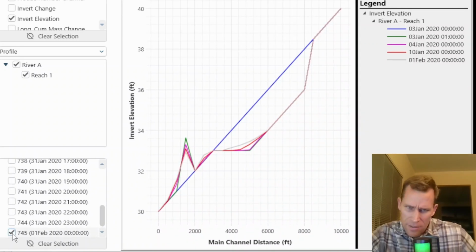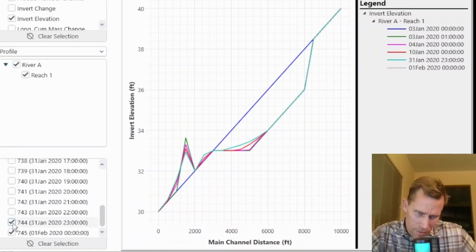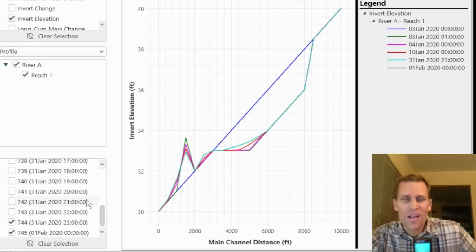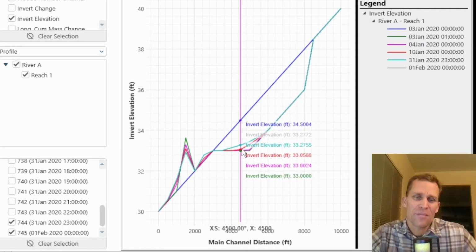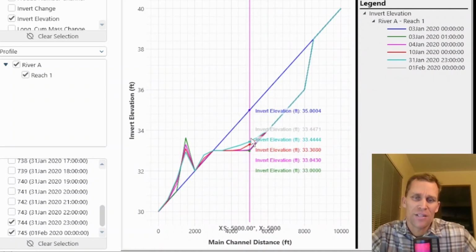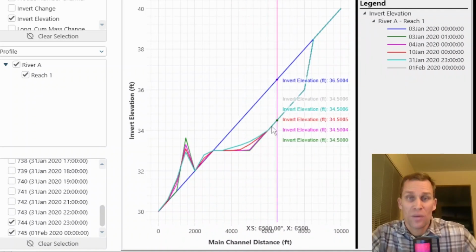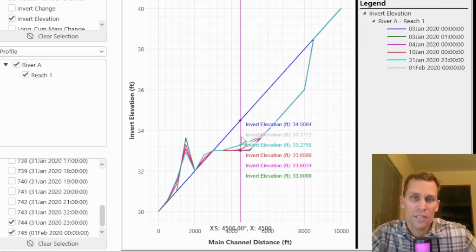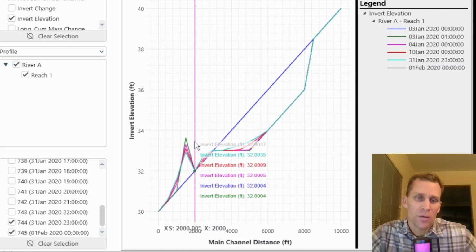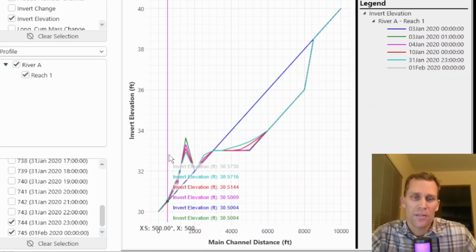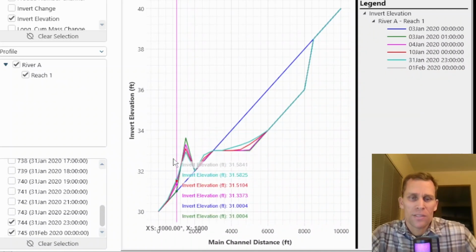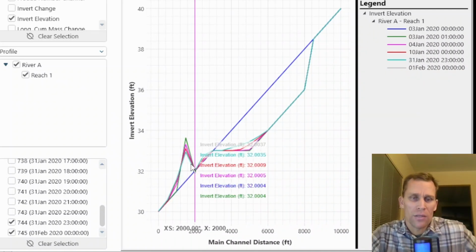Okay, I can't see that because it's the light gray color. Let me just click on the cyan. Okay, I still can't see that really well, but we can see that there is sediment buildup in the location where it was dredged. Obviously, a lot less with 300 CFS than with 100 CFS. And then the downstream location where that material that's been re-entrained gets redeposited. Very unnatural what's happening here, but cool that we could use the tools and demonstrate with this example with dredging in HEC-RAS.